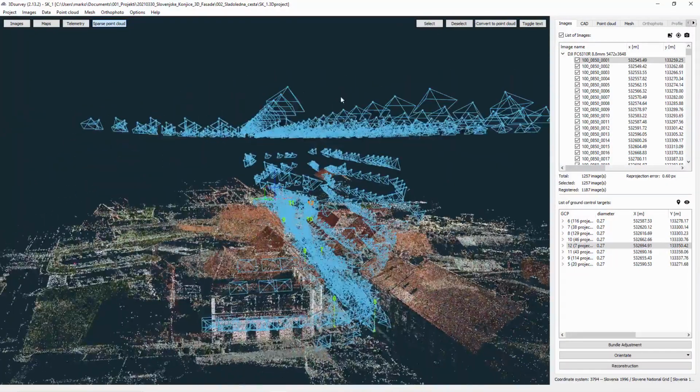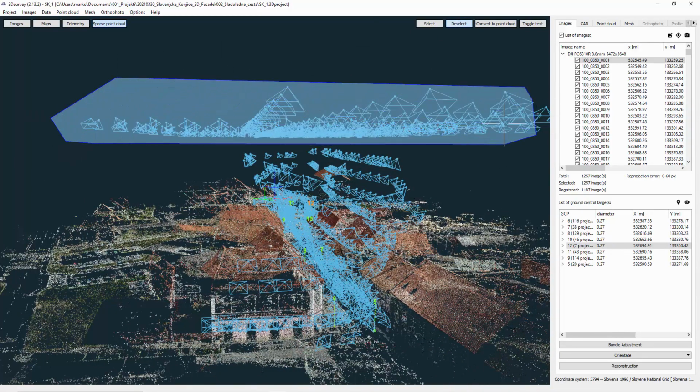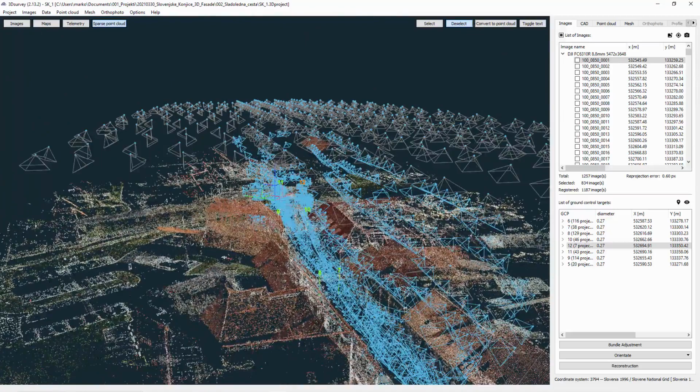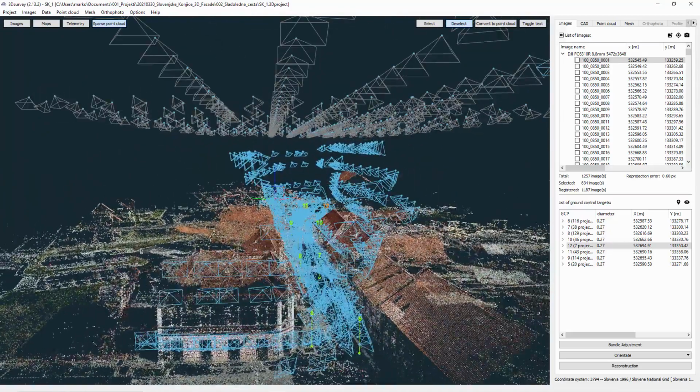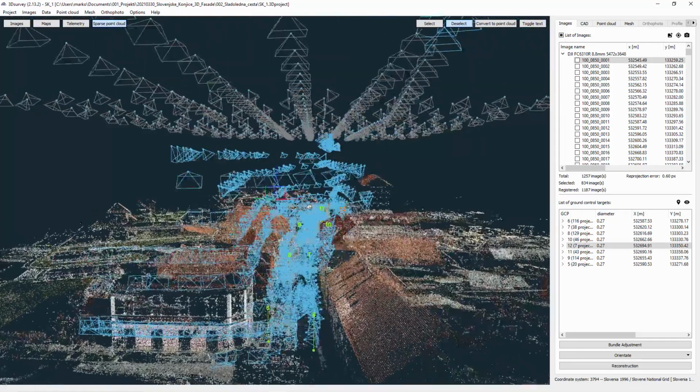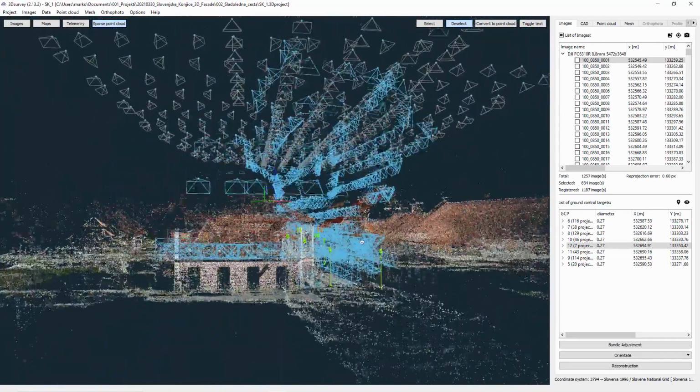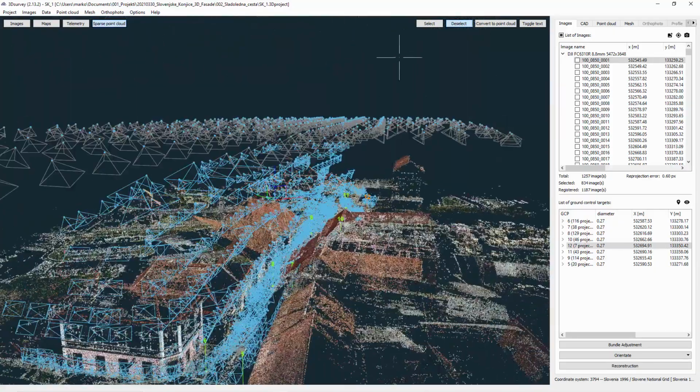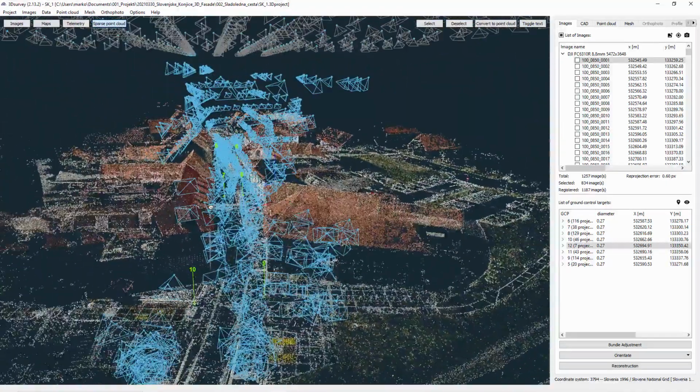So here first the double grid mission. Let's maybe deselect this one. Okay, so this was the double grid mission, and then I just go with a manual flight, flying in a row, turning the camera a bit down and triggering side images. The first double grid mission was at 35-meter flights, then I go to 30 meters, 25, 20, so every 5 meters I go lower and try to take the best side images to get the most detail out of it. The end results must be pretty detailed, accurate 3D models with a resolution of 2 or 3 millimeters, so super accurate.